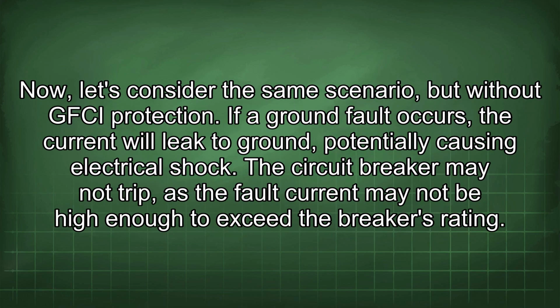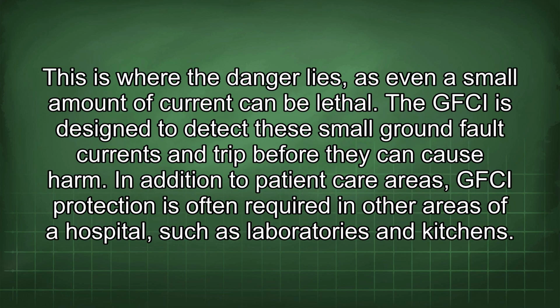Now, let's consider the same scenario, but without GFCI protection. If a ground fault occurs, the current will leak to ground, potentially causing electrical shock. The circuit breaker may not trip, as the fault current may not be high enough to exceed the breaker's rating. This is where the danger lies, as even a small amount of current can be lethal. The GFCI is designed to detect these small ground fault currents and trip before they can cause harm.